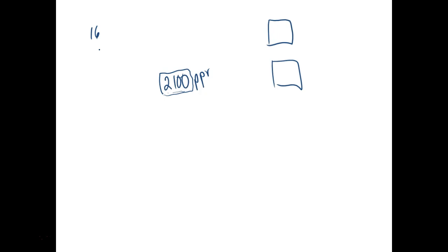So what we want to do is find the number of revolutions on the output shaft. So I'm going to take that 16 and multiply it by 131.25, and this comes up and gives us 2100. So that's what the encoder gives us: 2100 pulses per revolution on the output shaft, right? But it's got a lot higher torque. I can't stop this motor because the motor's running real fast, right? You understand?